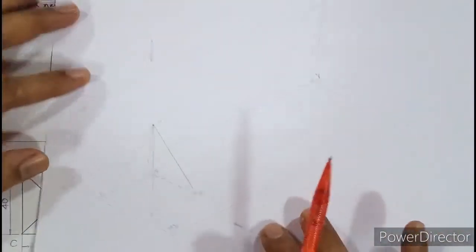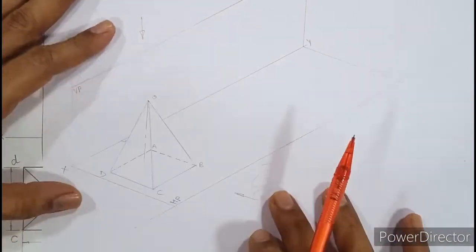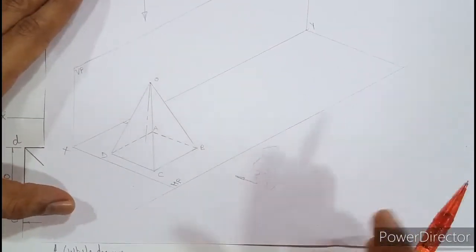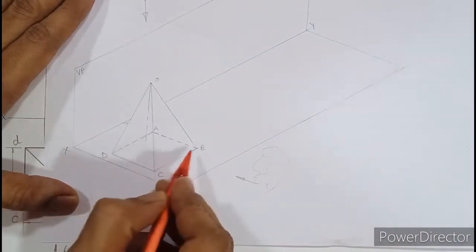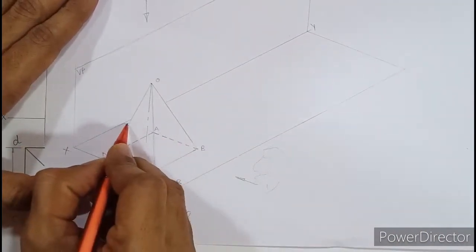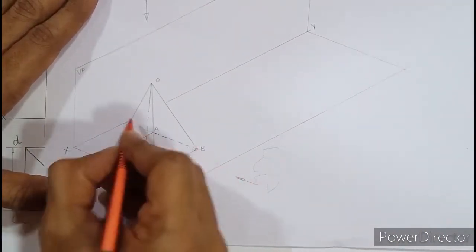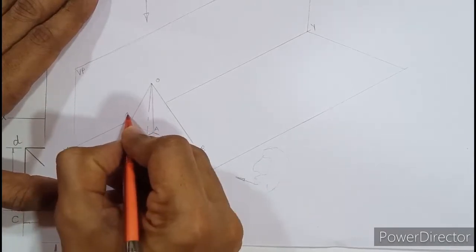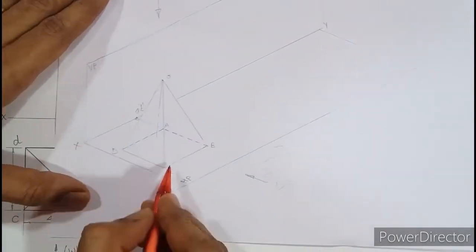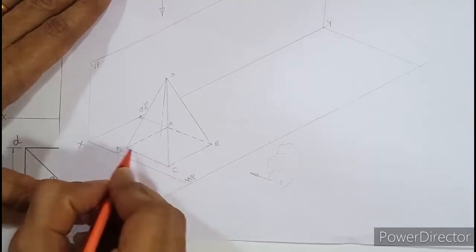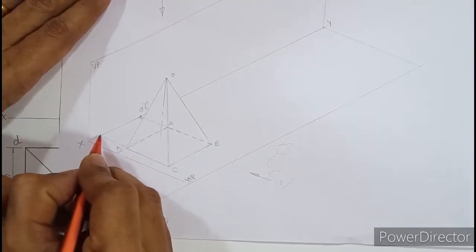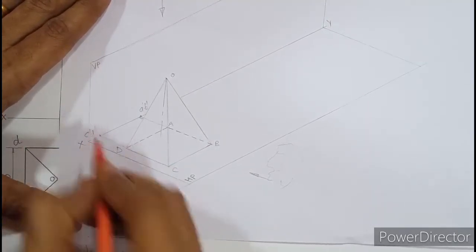Okay, so let us refer to this diagram, what is being drawn here. Try to visualize from the front. If you look at the projection of A and B, in the front view A and B will coincide and there is a single point A dash B dash. Why is it dash? Because it is the front view. C and D will coincide and here you will get a single point C dash D dash.